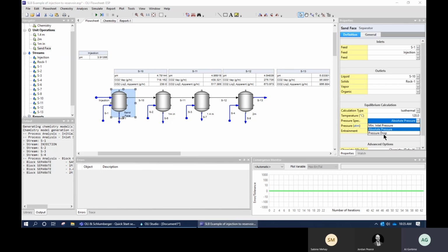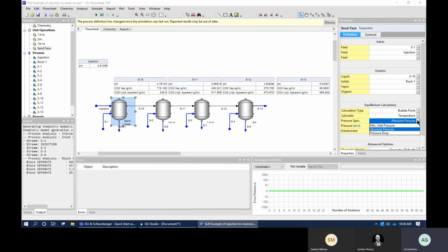do this at the bubble point. Okay. So we could see, for example, how the pressure increases. So we can do the bubble point pressure. Now we can see how the pressure increases as we increase the loading into this fluid. Assuming that the volume remains constant, we're injecting fluid, there should be a pressure increase.